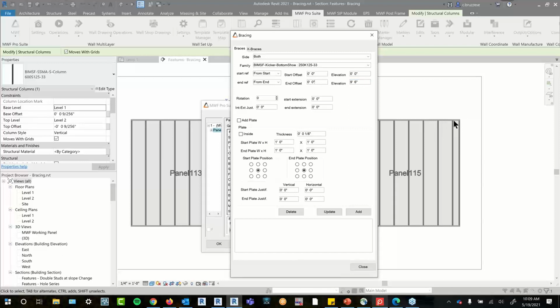I'm not going to go the full height of my stud since my bracing, you'll see in a minute once it's actually modeled, it'll be easier to look at. But it overlaps with the center. So that's why I'm going to drop it just about 6 inches, so the corners of my flat strap aren't sticking out of my wall. It'll make sense in a minute, I promise.